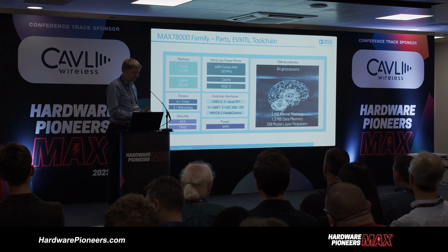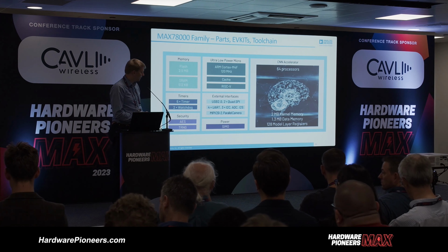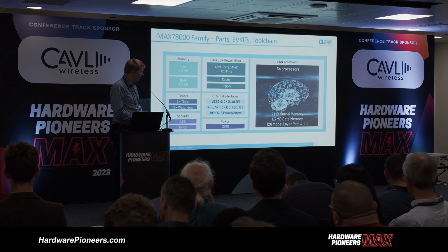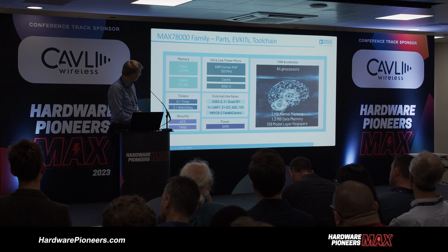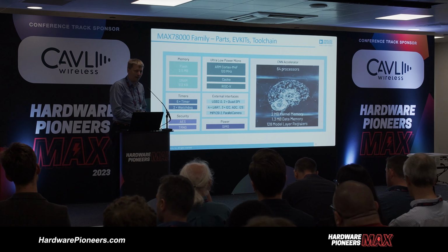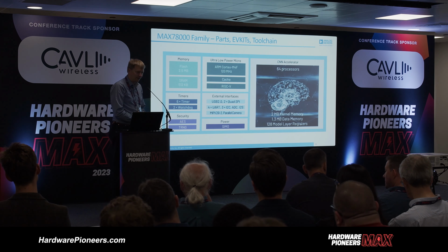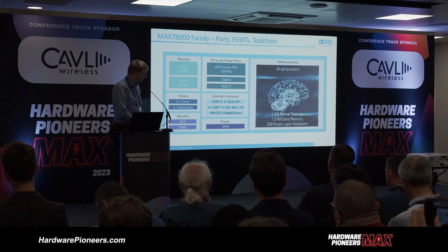So this is the MAX78000 family. It's on the first slide. It's a standard ARM Cortex-M4F microcontroller. So the left part of that block schematic is just an ordinary MCU. It's equipped with standard flash and all the peripherals you would need, for instance, a CSI-2 camera interface.